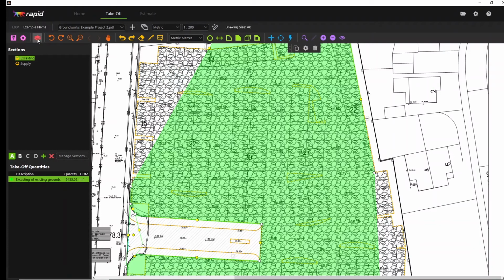To actually remove the background, you need to go into your drawing layers and come over here, and you'll see any layers if they are available, so you can go through and start to remove the different aspects of the drawing. This can be really helpful at times, as you are able to remove irrelevant bits of information to make the drawing a lot clearer if it is quite a busy drawing. My particular drawing didn't have any of those available to us, but always give it a check. It is always worth having a look because you can make your life a lot easier by removing them.